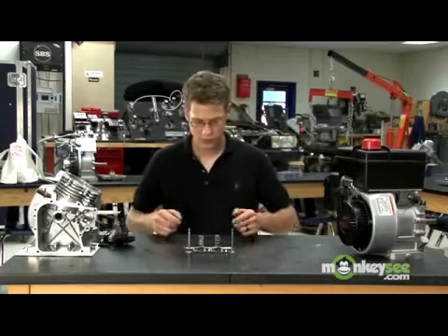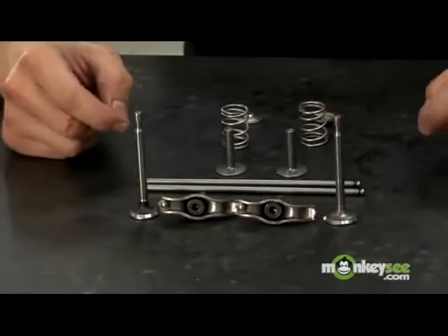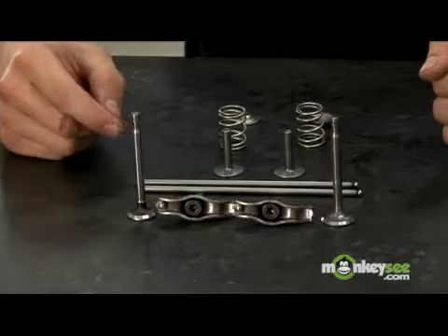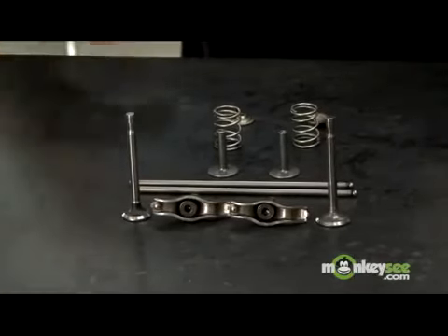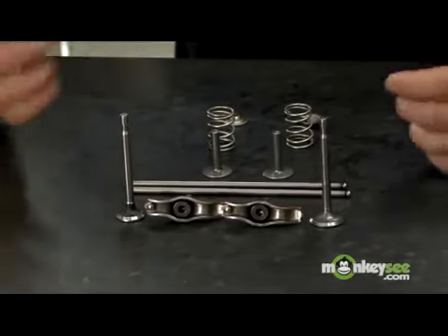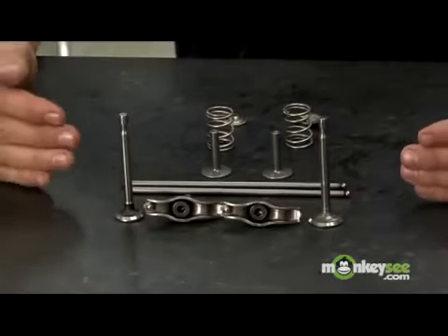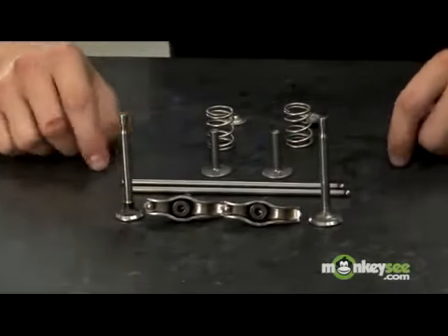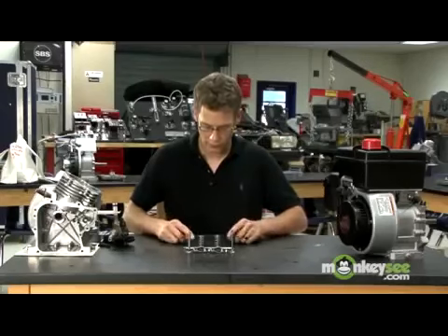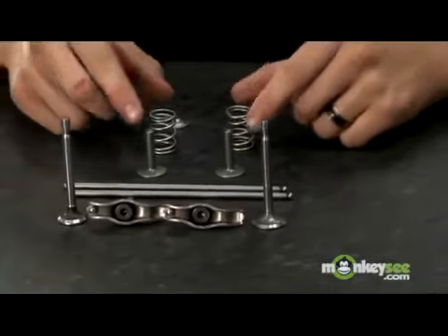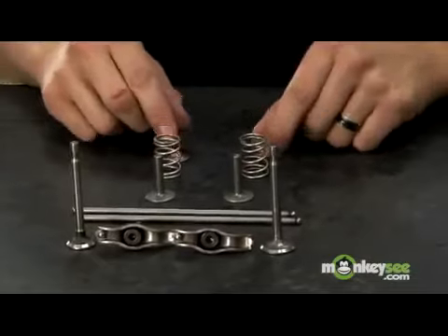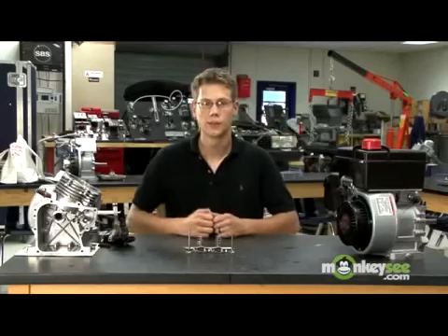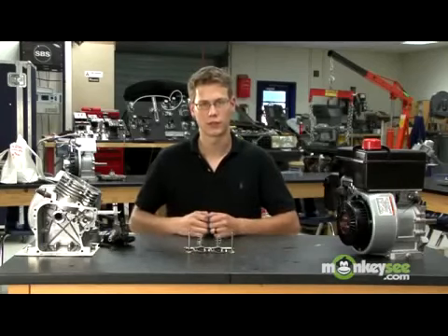This valve system consists of 2 valves. We have our inlet valve, which brings gas and air into the combustion chamber, and the exhaust valve, which expels the exhaust vapors out of the engine to prepare it for its next cycle. We have rockers, much like in a car. We have lifters. We have corresponding hardware for the lifter system. We have valve springs and the valve spring caps. All of these components work together and can be better illustrated with my engine model.